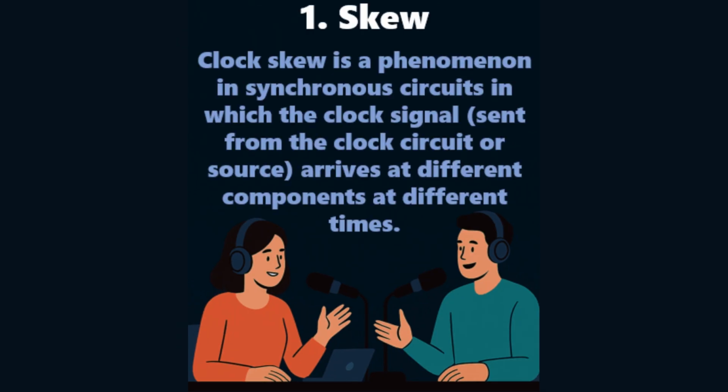That's a perfect analogy, actually. The clock signal is the heartbeat. Imagine billions, literally billions, of tiny components inside that chip. They all need to work together, perfectly synchronized. The clock is this regular pulse sent out from a central source. It tells all the synchronous bits, like flip-flops, think of them as tiny memory cells, exactly when to grab and process data. Now, clock skew.